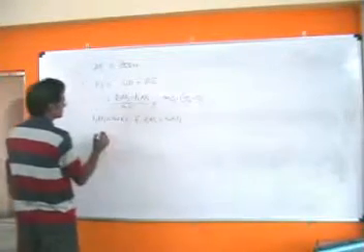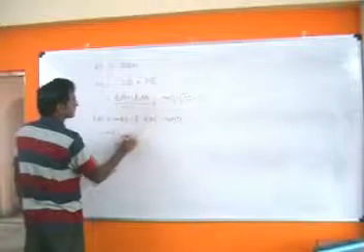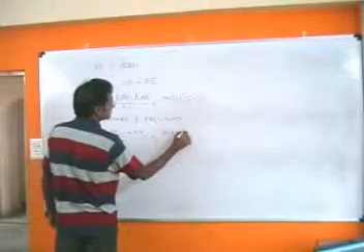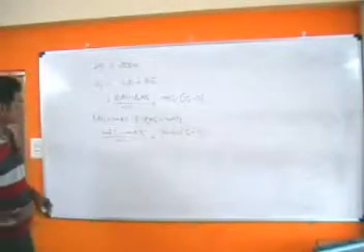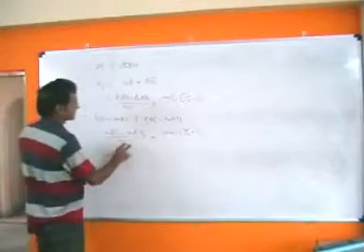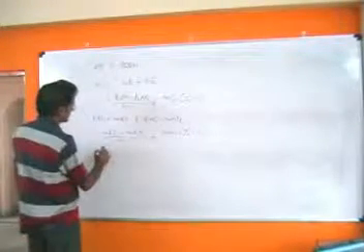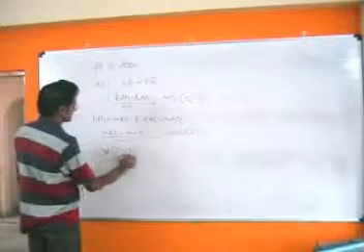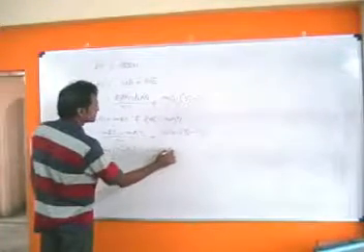So we replace these two terms with (mR T1 minus mR T2) by (n minus 1) plus m Cv (T2 minus T1). So what we can do is take mR common, leaving T1 minus T2 inside, by (n minus 1), plus m Cv into (T2 minus T1).